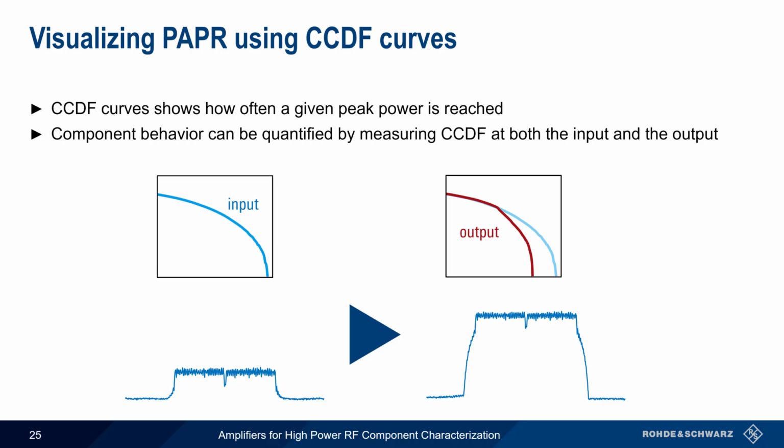It's important that an amplifier placed before the DUT input not be in compression, since this would make it difficult or impossible to separate the distortion introduced by the DUT from the distortion created by an overdriven amplifier at the DUT input.